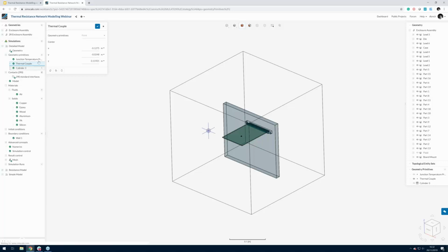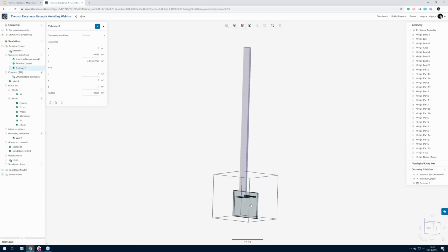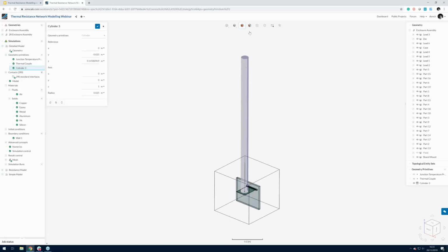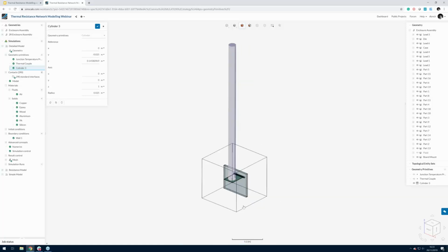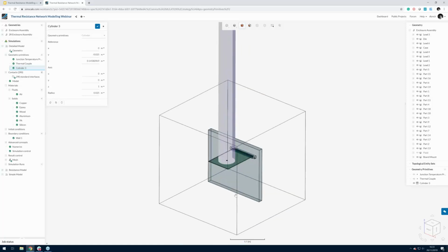And finally, we've got a cylinder that I've located here. It extends ridiculously beyond the domain, but this is for mesh refinement. When we finally get onto designing the mesh, this is what we use to refine the plume. In case you're not familiar with SimScale at all, or this particular analysis type, SimScale automatically defines contacts.